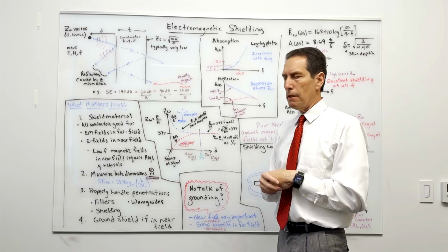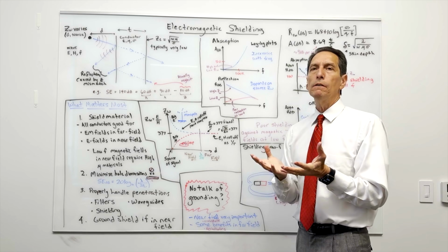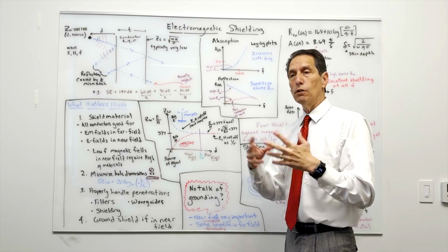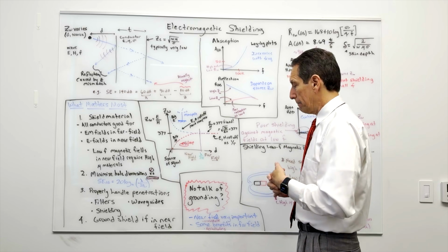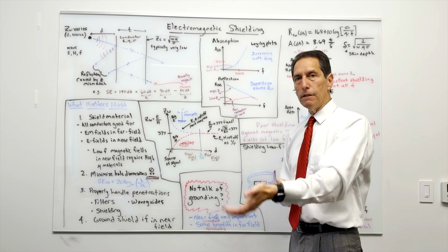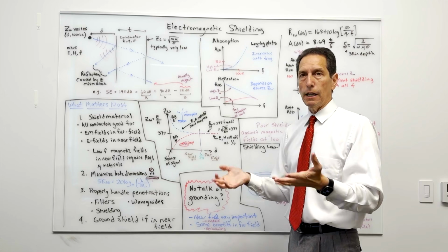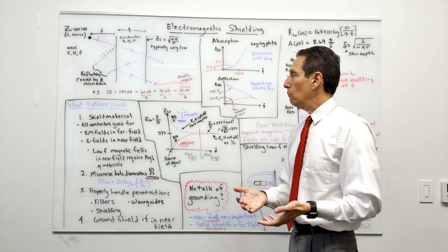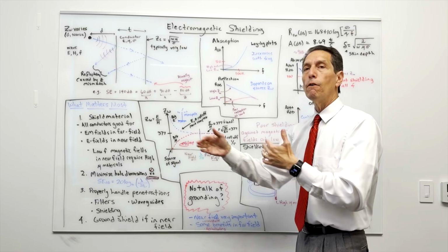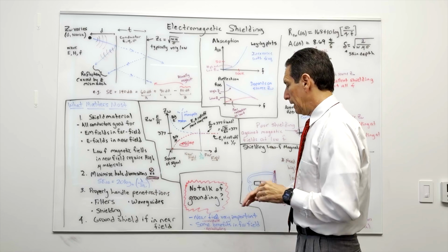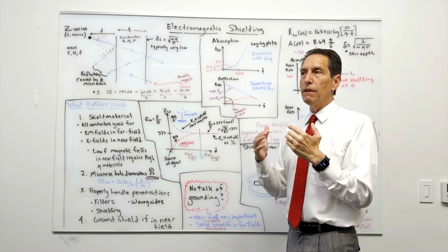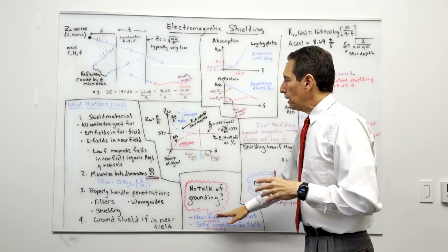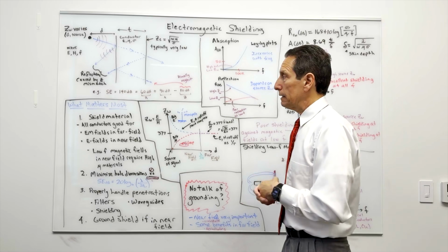I've done a video or two on this. So for an EMP, I often say it doesn't matter much if you ground your shield. And in reality, it doesn't. You can measure the energy is about the same either way. It's not to say there's not some benefits of grounding. Sometimes it's important to ground for safety and other reasons. But the benefits are much more limited when you're in the far field, when you're far away from the source, okay? So it may help prevent some re-radiating where energy gets on the shield and then radiates around a little bit. But in general, it's much less important, right? Which is why I say that.